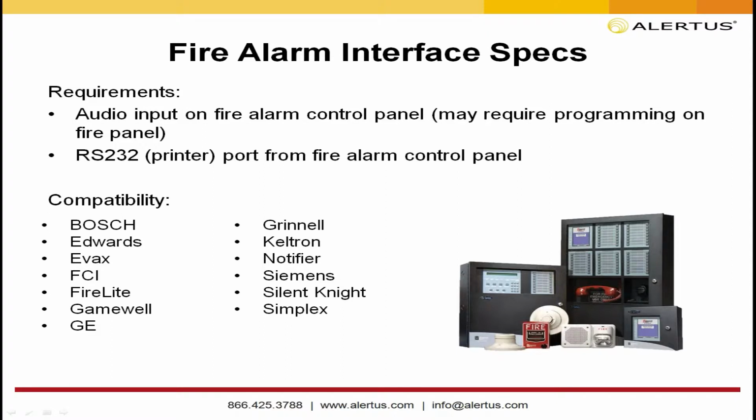Just to finish off the fire alarm integration, we have integrated with many different fire panel makers, as you can see on the slide here, namely Gamewell, GE, Siemens, Silent Knight, Simplex, all those major ones. But the main factor you would need to ask yourself if you want that type of integration is, does my fire panel have an RS-232 port that it outputs that code out of? If it does, we are about 99.9% sure that we would be able to integrate with it and disseminate that message out to your entire facility.